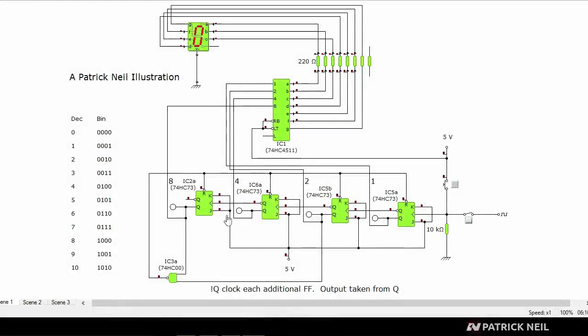These four devices are called flip-flops. Flip-flops are circuits that are able to latch their output in a specific state whenever a sequence of voltage is placed on its input. This sequence can either be low followed by high or high followed by low. If the sequence is from low to high, they are called positive edge flip-flops. And if the sequence is from high to low, they are called negative edge flip-flops.